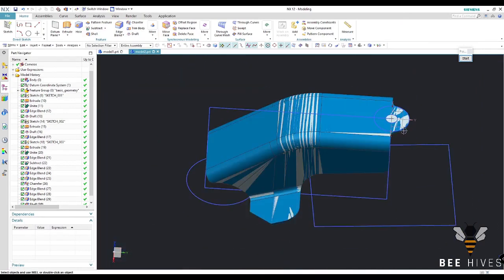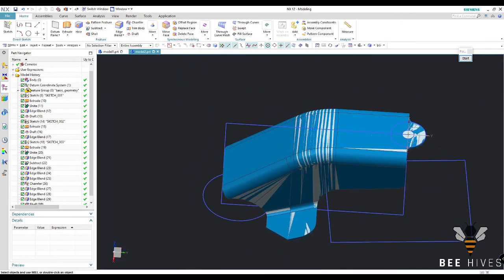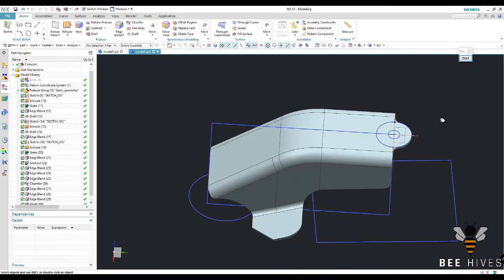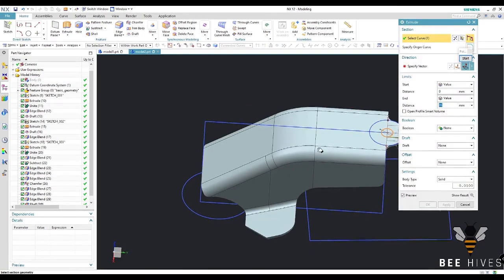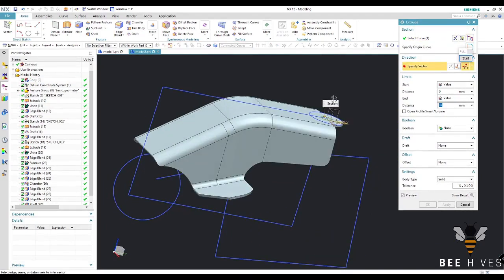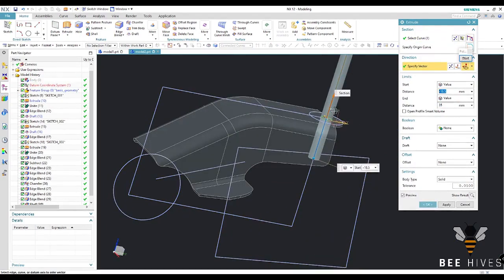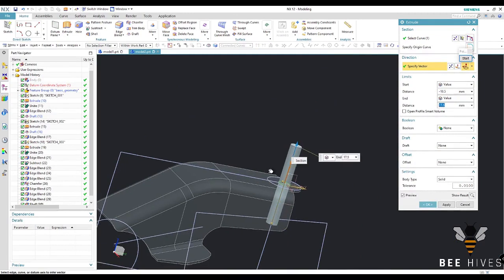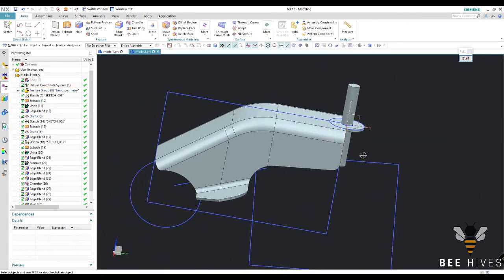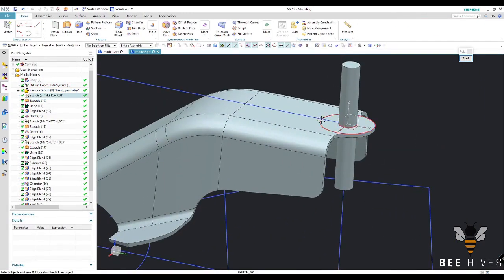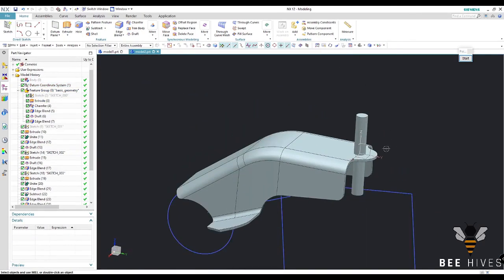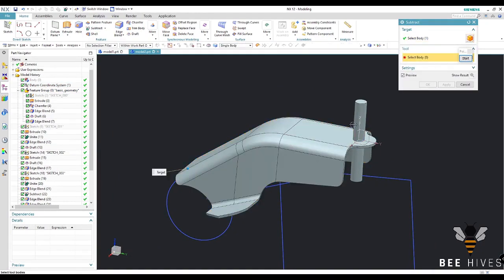Now we are left with the hole, so you can simply extrude it again, the whole geometry. Always remove the hole afterwards, after the shell, because if you do it earlier you will have to edit the shell on multiple faces, and this is what I don't prefer.